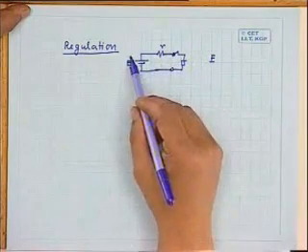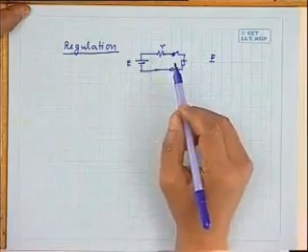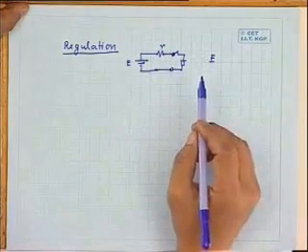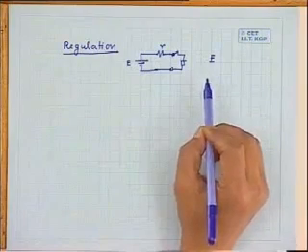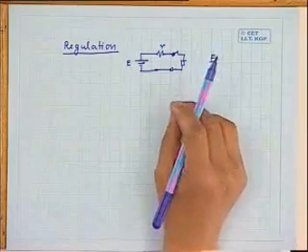However, when you load the battery, this voltage will certainly be less than E because of the IR drop in its internal resistance. Therefore, what we note here is that the voltage available across the terminals of the source during no load condition is different from the voltage available when it is loaded, is it not?